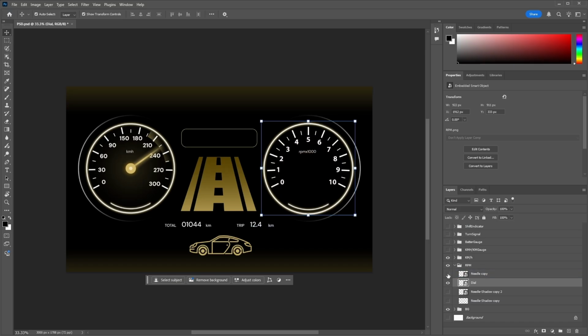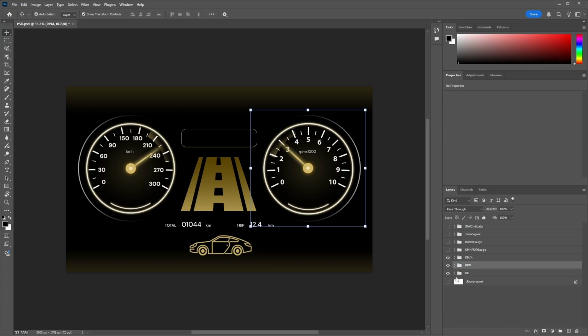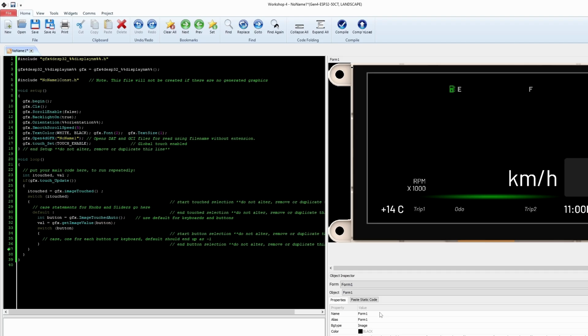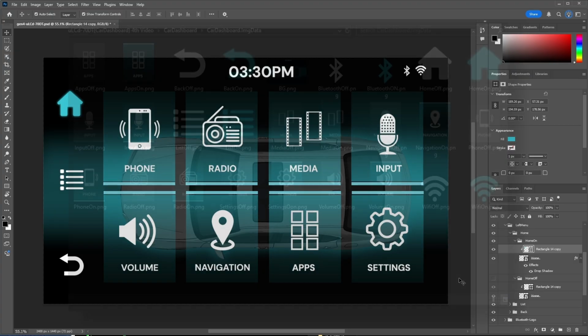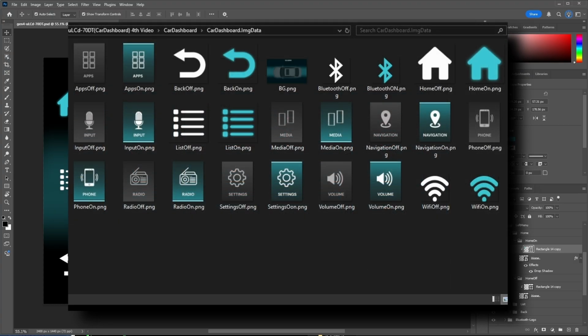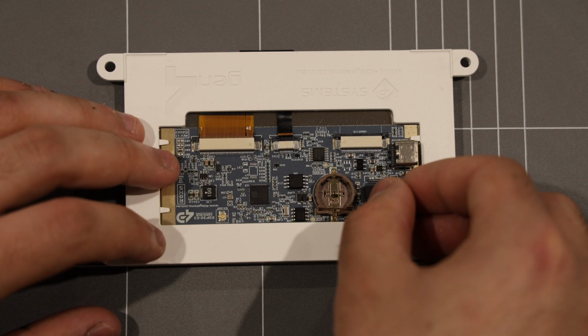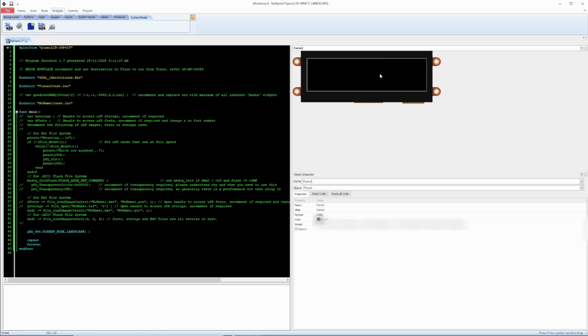Before we talk destinations, we need to understand something important. A project has two parts. First is the program. These are the actual instructions that the processor runs. It is usually very small in size, only a few kilobytes. Second is the supporting files. Those are things like your graphics, fonts, strings, and audio. Supporting files are always copied to the SD card. The destination options only affect the program, not the supporting files. That's the key difference. So let's get into the different options and what they mean.